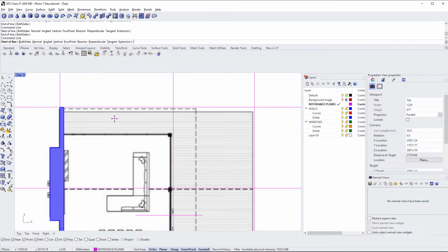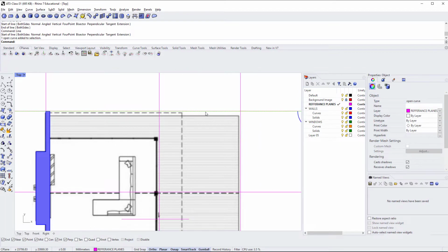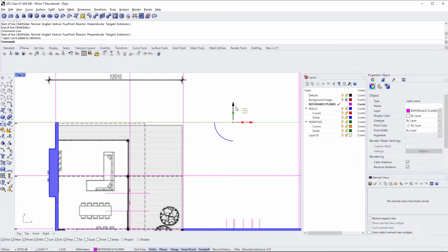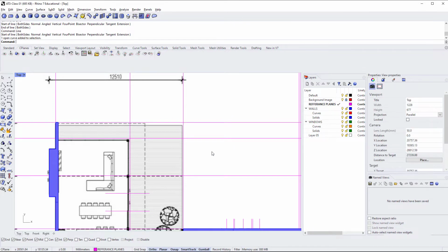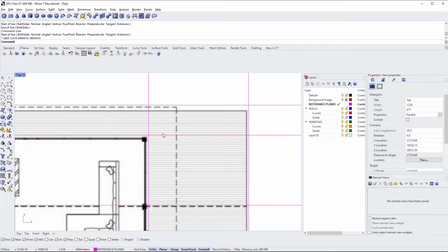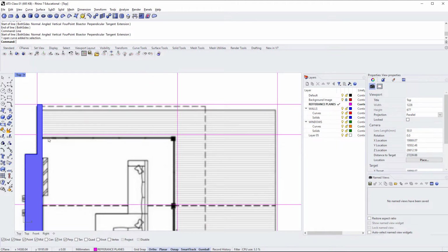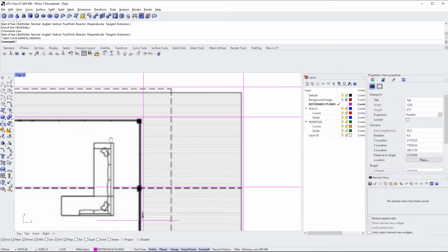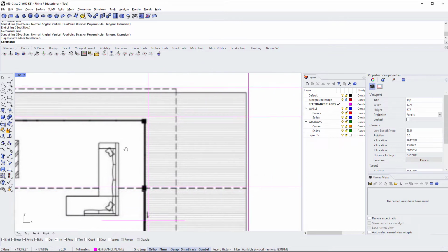And to do that, I'm going to take this line here, hold down Alt, click the green arrow, and go -1500. And that's going to be our glazing for this wall here. I think the original is like 1688 or something, but just using round numbers for argument's sake, we'll make that 1500 overhang or a 1500 wide deck component, just for nice even numbers.